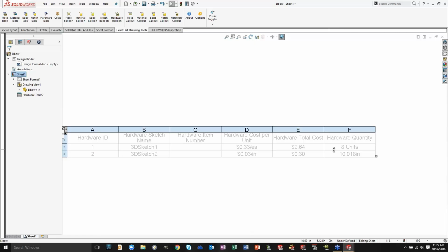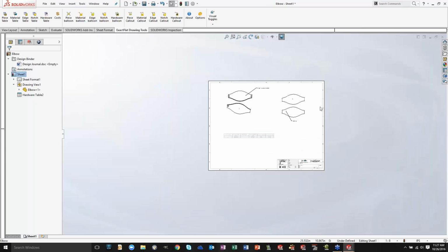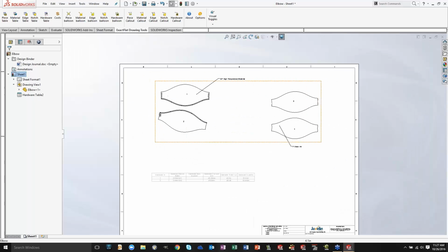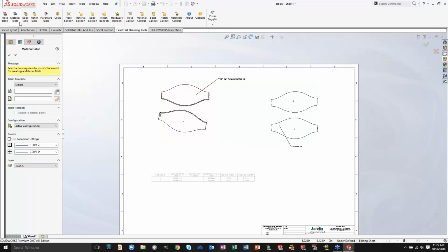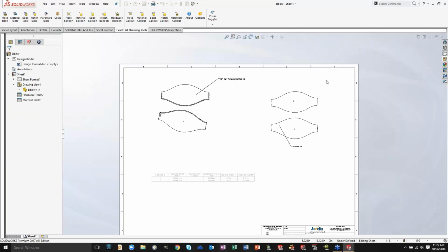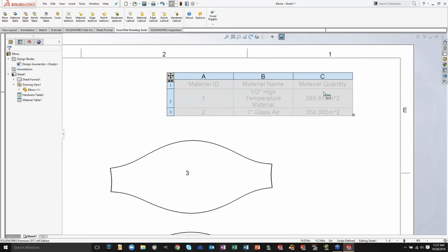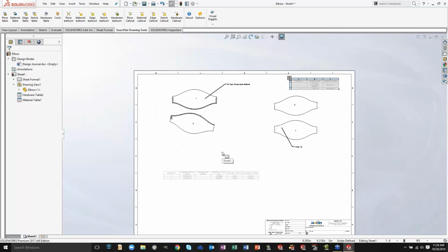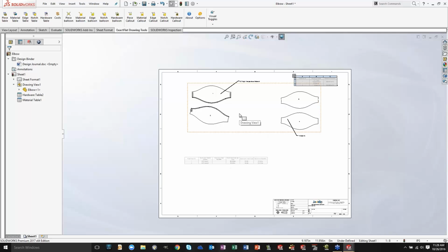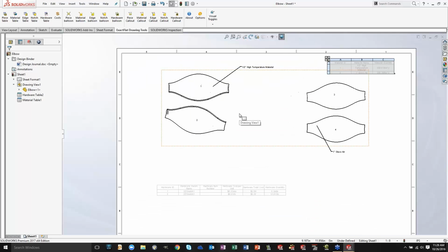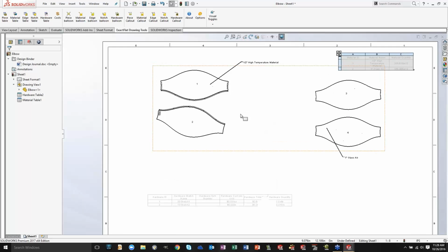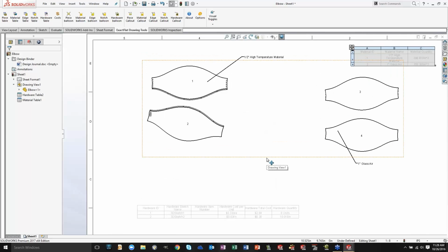So you'll notice that for the hog rings, it has the number of units, and for the Velcro, it's got the total length, so we know exactly how much we need to use in this particular pattern. We can also do things like material utilization. So we know how much material we're going to use on the marker itself, but maybe we want to see how much material is being used on this actual marker. So on both different markers, we can see how many, in this case, square inches of material we're using for both of these patterns. So some very powerful analytics, as well as costing information, and getting you right from that design straight through to documentation and to your cutter.